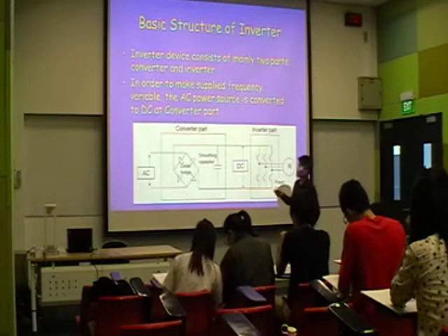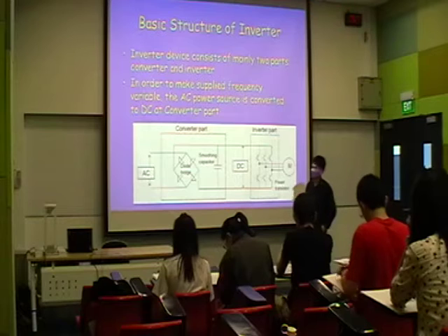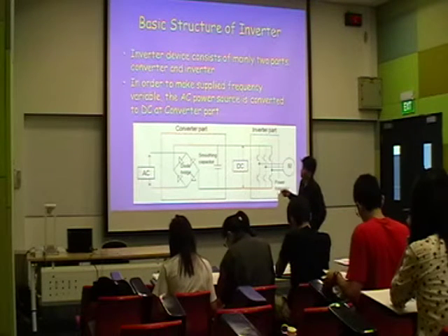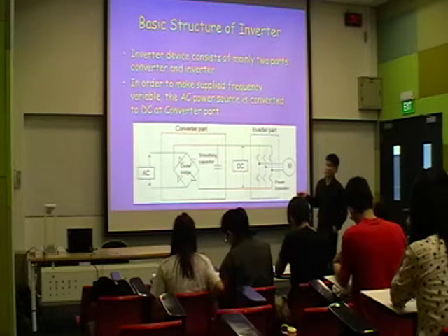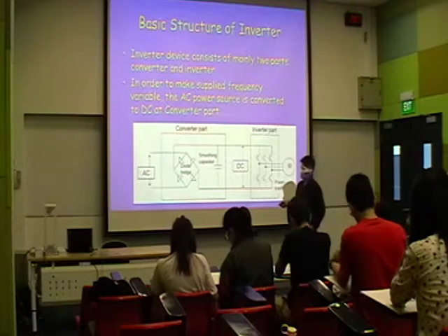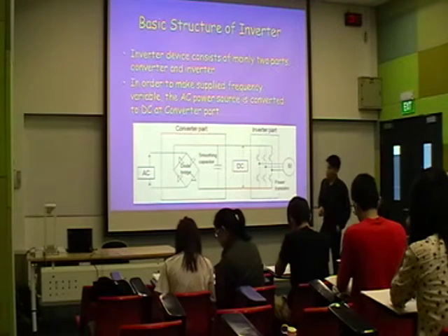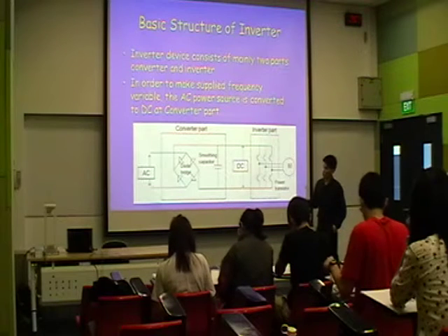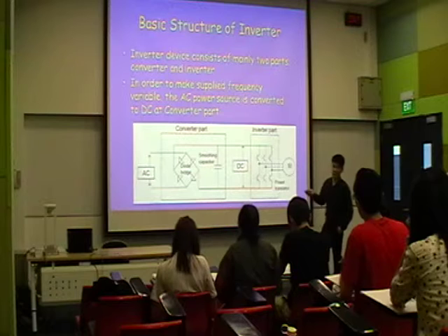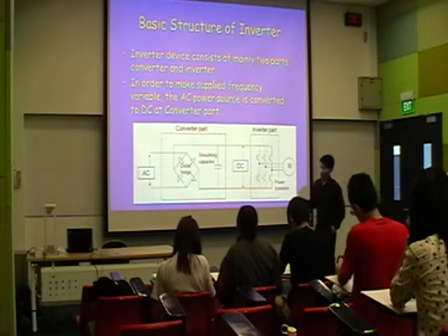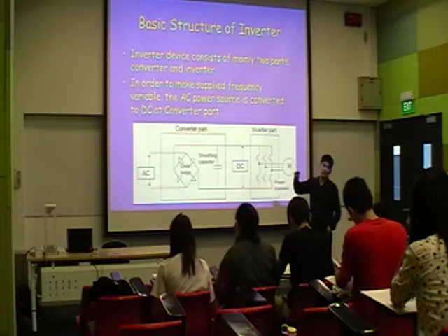In practice, how we configure this type of system, you will see that the inverter consists of basically two parts that I mentioned in the previous slides. The AC, which is the three-phase power source, goes through diodes. This bridge helps to rectify the sine wave to a waveform that appears almost like a constant DC line.